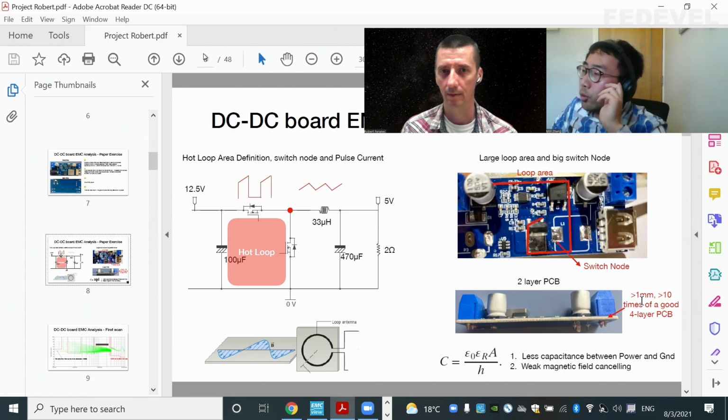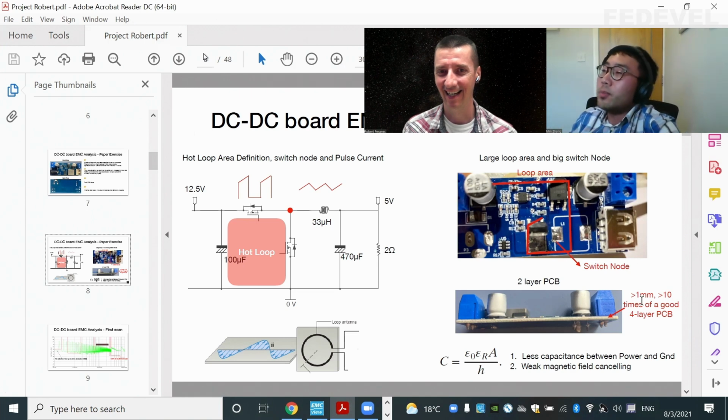I've seen people say, oh, I'll leave a cut-off area on the second layer. But then that means your noise can penetrate into your second layer and affect your third layer performance. I think there is some discussion on the internet about whether cutting out some area under the inductor will improve performance and EMC and EMI.